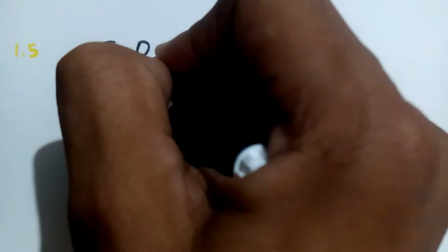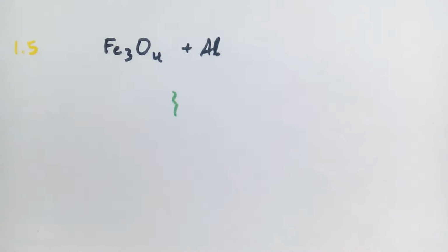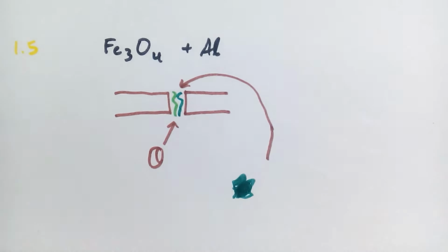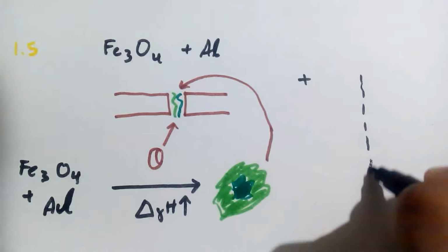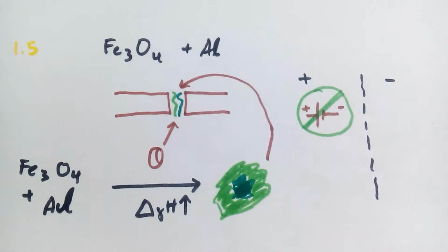Fifth and last is thermochemical or thermite welding. Here, coalescence is achieved by heating with superheated liquid metal and slag resulting from chemical reaction between metal oxide and aluminium, leading to an exothermic reaction. Advantages include no electricity requirement, but it is only applicable for ferrous metal parts of heavy cross sections.